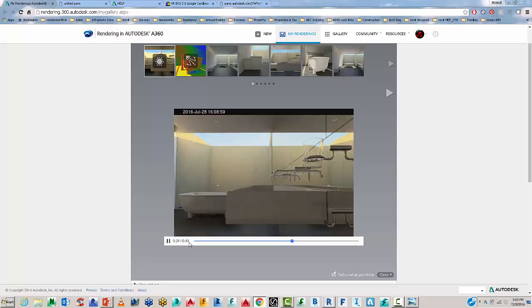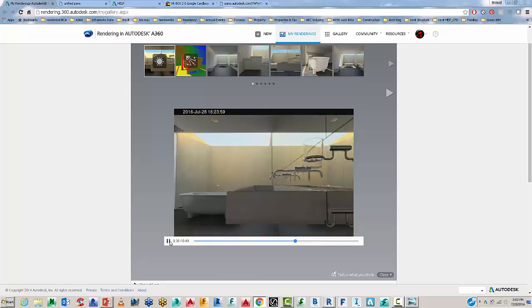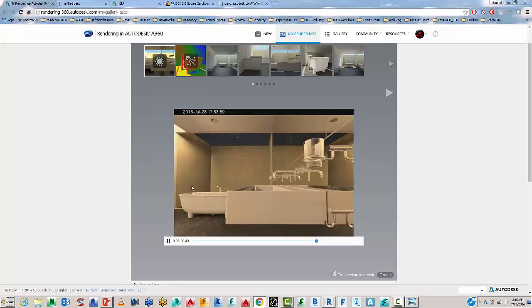And of course, if you want this a lot sharper, you can re-render the still image as a larger image, then run the sun path study, and you'll get an idea of what it's like from morning to sunset. And what you're noticing here, if I just go back a little bit, at night time the lights will come on. So if I go and play that, as the sun disappears, the light in the light well will come on here, and we've got our nighttime illumination.